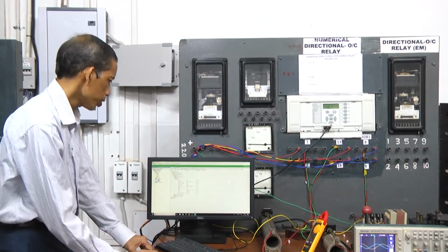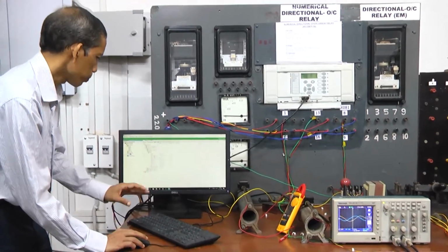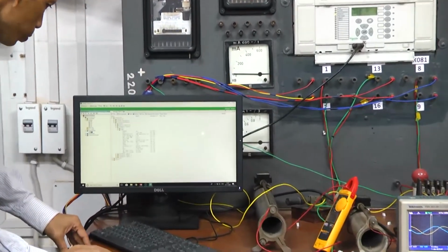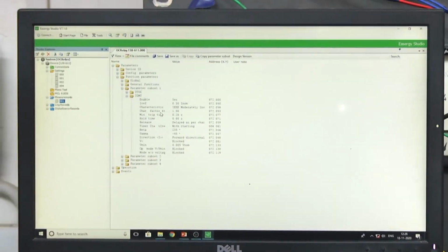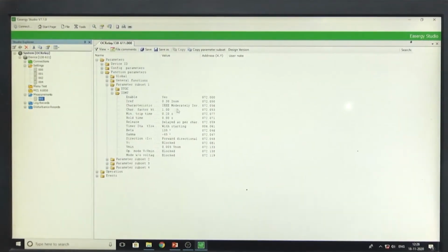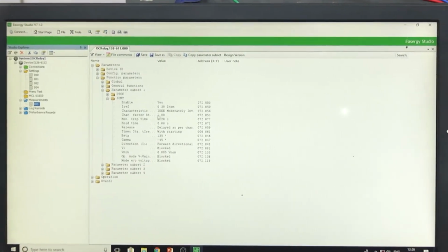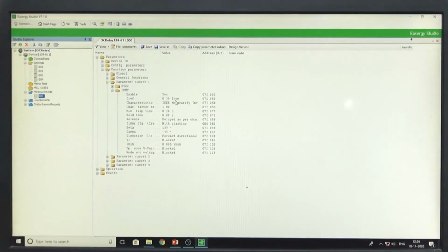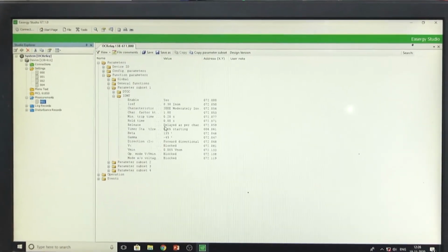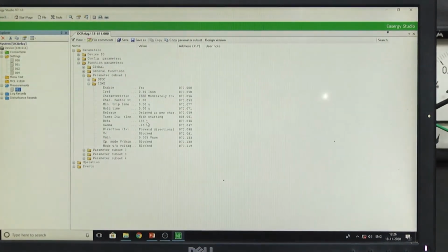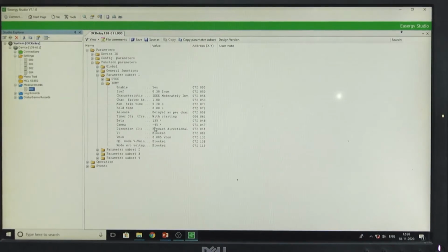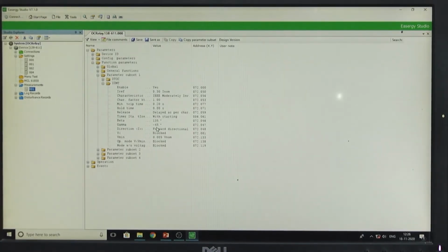If you see here the settings for the particular MiCOM relay, we are considering IDMT characteristics, IEEE moderately inverse, and our setting here is 0.3 of I nominal, where I nominal is 5 ampere. The beta angle is 135 degrees and the gamma angle is minus 45 degrees for this case. So, the first setting we have set like this for both the current and the voltage part.